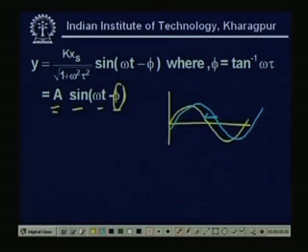Sometimes in many instrumentation systems, we will find that this phase shift is a nuisance. That means we have to kill this phase shift. In the case of leading phase angle, we have to use a lag network, and in the case of lagging phase angle, we have to use a lead network. Even though the circuit is very simple, with one resistance and one capacitance, I can make a lead lag network, right. So, this is my output, you can see here.